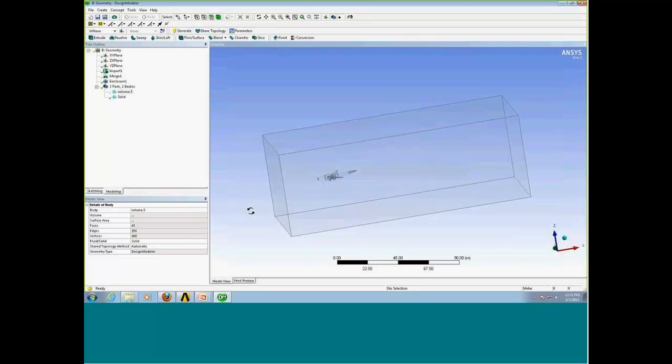So at this point, we've covered how we do this in ANSYS DesignModeler. Hopefully, we've showed you a couple of things that you could go back and use on your own. A few points to remember. ANSYS DesignModeler allows you to do these geometry simplification tools on any CAD part that you import without affecting the original CAD file.